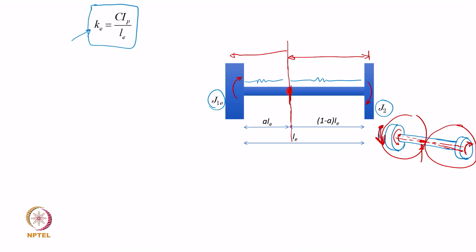These are all the conceptual discussion of how they will oscillate or vibrate, but it is sure that when they vibrate at the second natural frequency, there is going to be a location along the length of the shaft where the twist will be 0 and the left hand side disc will move in a direction opposite to the direction in which the right hand side disc oscillates. So, they are going to simply oscillate in opposite phase, which gives us a position of 0 displacement somewhere here. We do not know where exactly the node position or 0 displacement position is.